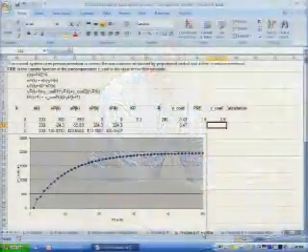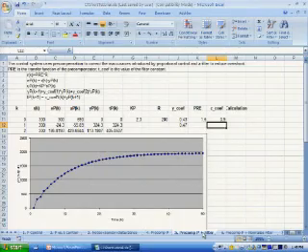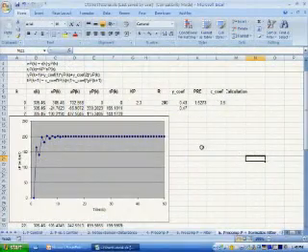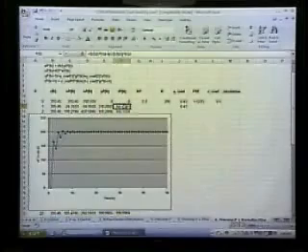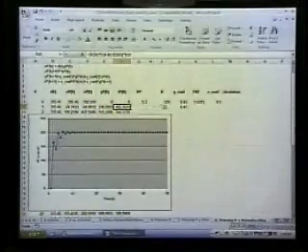Now, the problem is that the system also got slower. So it was inaccurate and it was slow. Here's the normalized filter. Okay, so we had 2.3 there. And now when we do it, we get the right answer because we now have the normalized filter, which is here. So that has the C and then the 1 minus C in it. Okay, so we've got all that, so that's good. The problem is that it's a bit slower than what we had before.